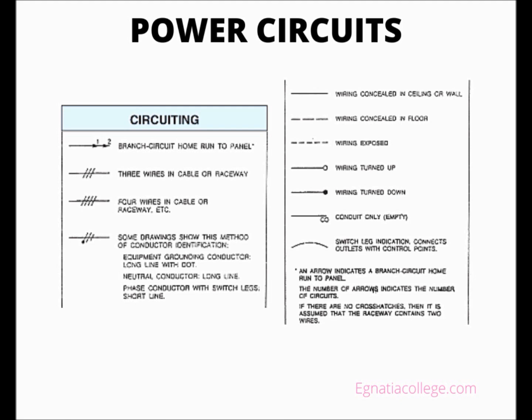The electrical installer will normally group home runs in a raceway with combinations similar to the following: 3-phase systems with 3 circuit wires and a common neutral in a raceway. Single-phase systems with 2 circuit wires and a common neutral in a raceway. Note: to reduce the harmonic problems caused by solid-state devices, nonlinear loads, many electrical designers are requiring separate neutrals with each phase conductor.